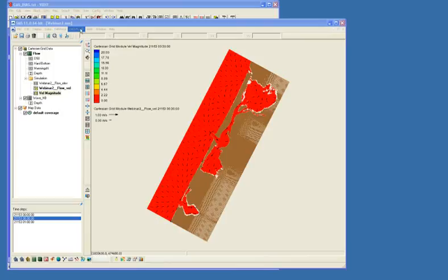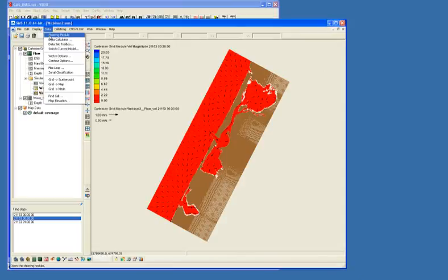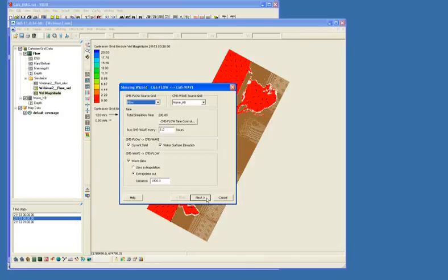So basically, the information that gets passed from the wave grid to the flow grid, if I go into that steering module again, it's passing the current, the flow velocities and the water surface elevation to the waves, and the wave information back to the flow.